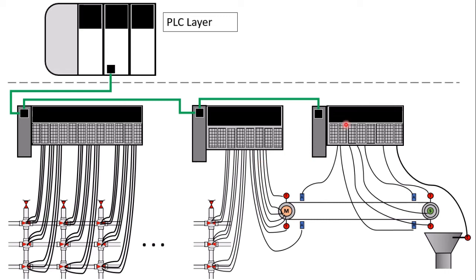These field network islands or connection points have digital input and output cards as well as analog input and output cards like a PLC rack. Of course, with new developments, the configurations and connections have changed, but if you are still learning, it is safe to think digital input and output as well as analog input and output. The new developments are still based on this concept.